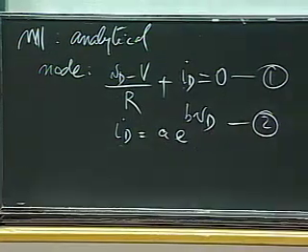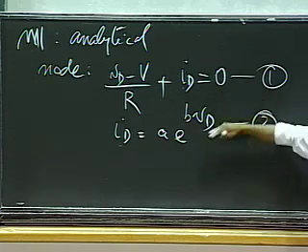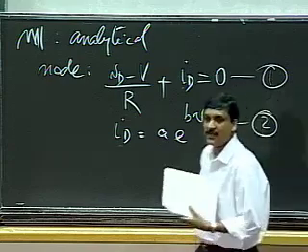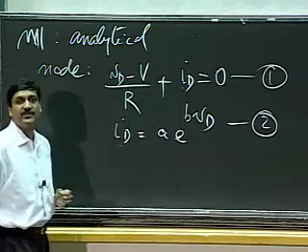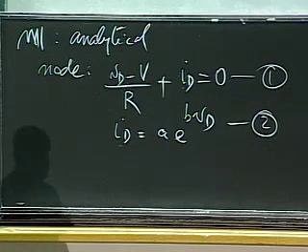You can now analyze nonlinear circuits. You get a bunch of equations, a bunch of unknowns, and you go solve. I have two equations here. VD and ID are my unknowns, and I can solve for them. Now, in general, with nonlinear circuits, it's often hard to get a closed form solution, so you may have to use a bunch of methods. You can try a closed form solution, or numerical solutions, or you can do trial and error.